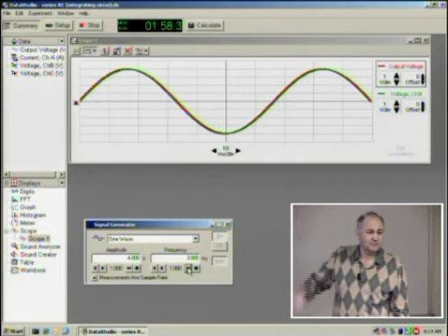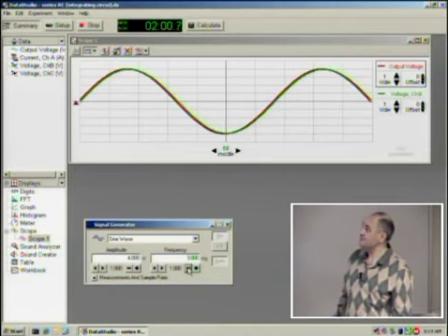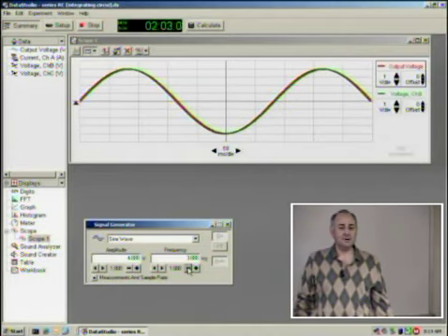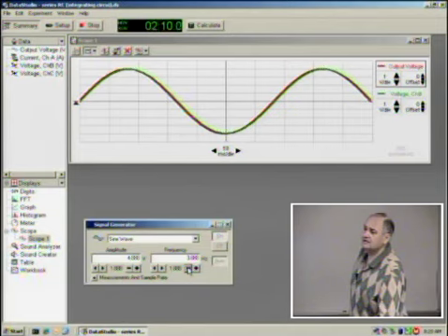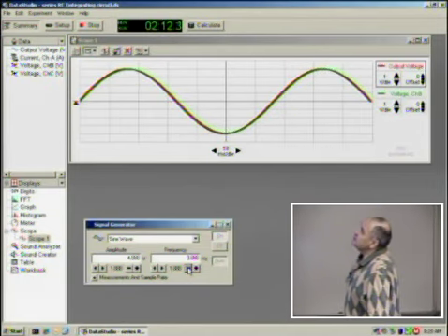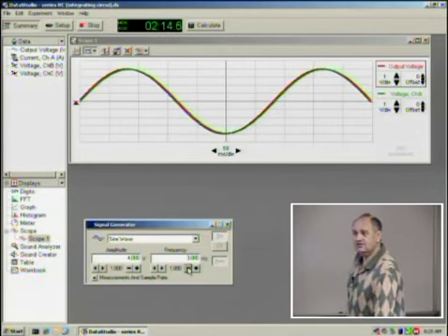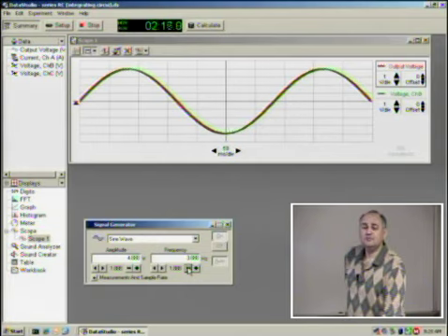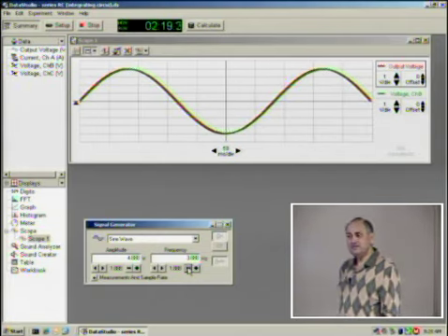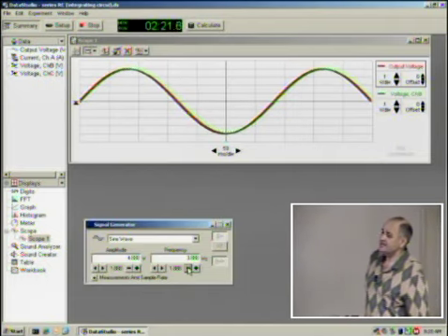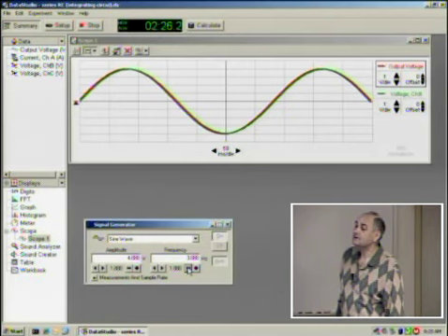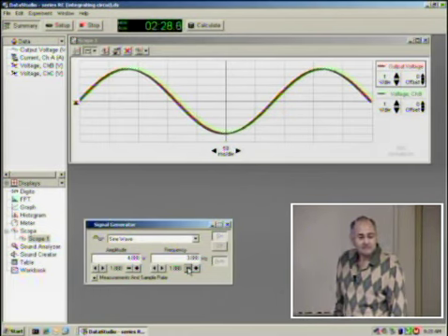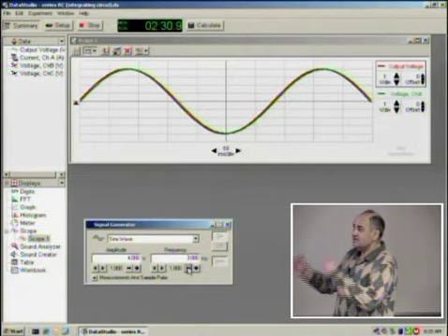Both scales, output voltage and input voltage, are 1 volt per division. So what is the value of input voltage, peak value of input voltage? Why don't you shout? 4 volts. Input, peak value of input is 4 volts. What's peak value of the output? Also 4 volts. Well, estimate the gain of the circuit now. How much? 1, right? The gain is 1.